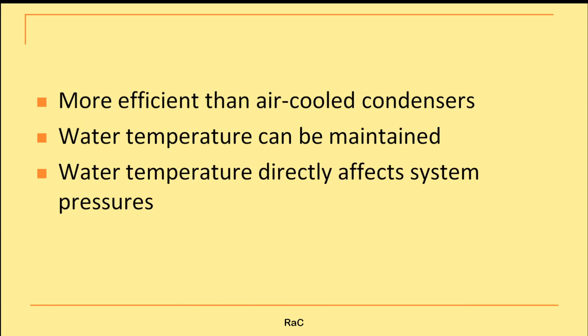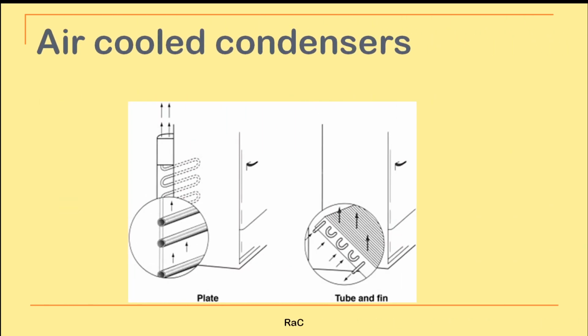When compared to the other types in the shell and tube category, it is more efficient than air cooled condensers. So water temperature could be maintained easily. Water temperature directly affects system pressures. So that is water cooled condensers.